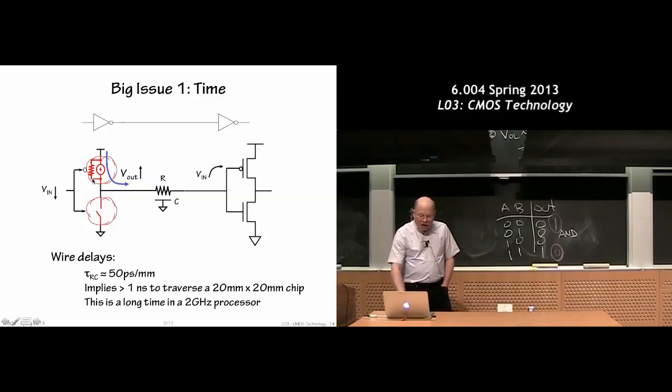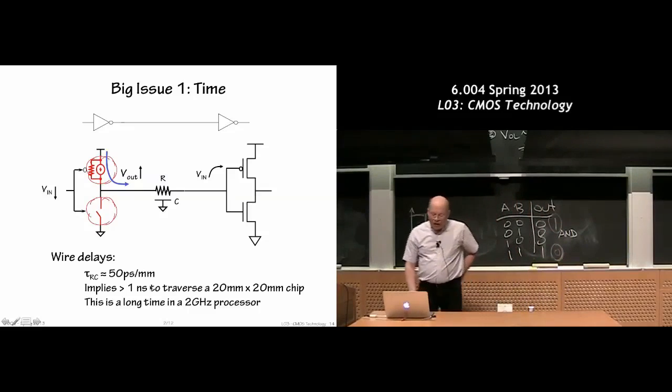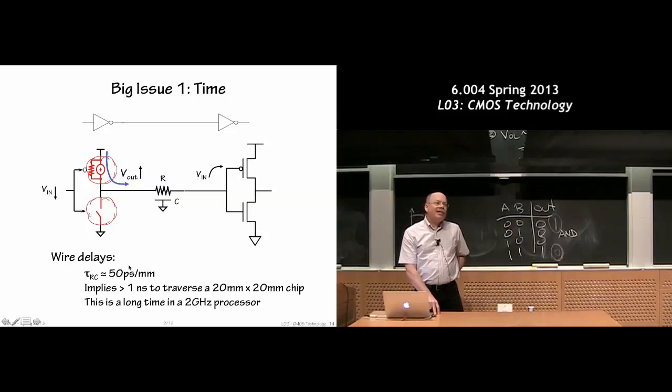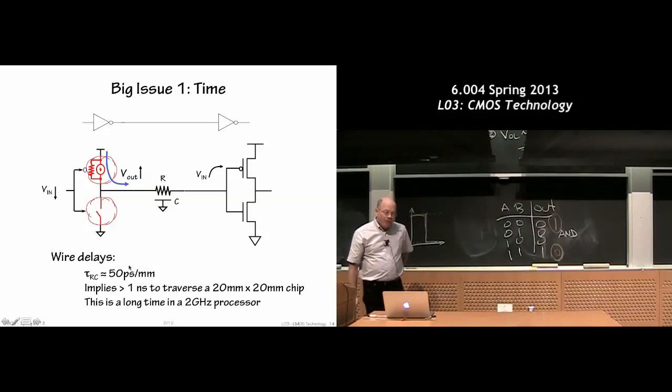Getting signals to go across the network and change the output of one of the logic gates might take on the order of tens of picoseconds, and then transmitting the signal down the wire takes about 50 picoseconds per millimeter. In other words, the speed of light along these conductors embedded inside these insulating dielectrics is not quite the speed of light. You might say, picoseconds, that seems fast. And the answer is yes, except your chip is probably 20 millimeters across these days, and you're trying to design a set of logic and transmission wires that all operate within 1,000 picoseconds. A gigahertz processor. Whoa, this is starting to be a challenge. So the fundamental limitations of physics keep things from going too fast. They're not infinitely fast.